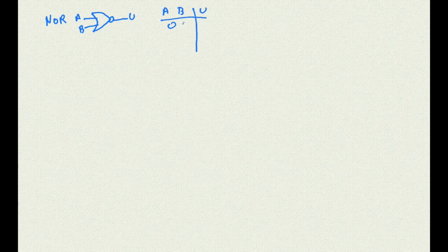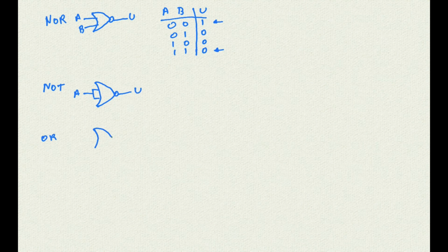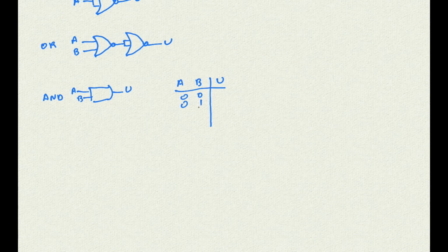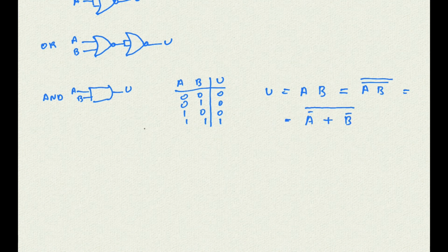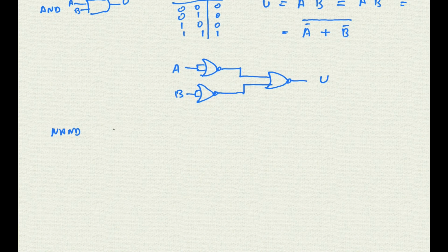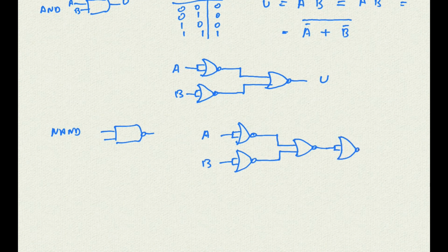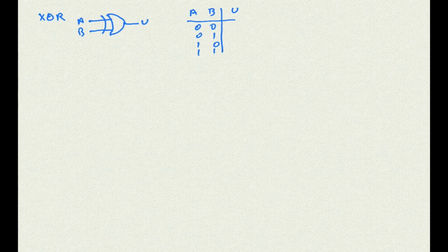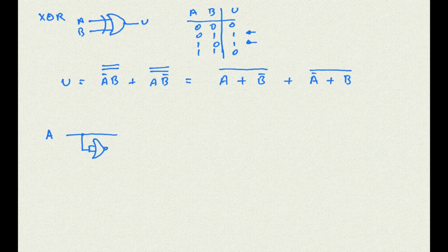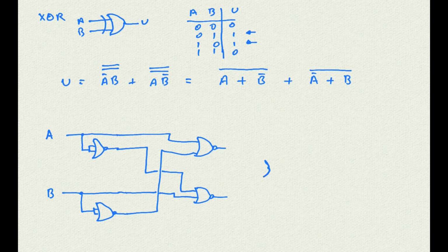One last thing that is left to do is to show you how to make any of the gates we studied using only NOR gates. The procedure is similar to the one we used for the equivalence with the NAND gate circuits, but this time we will need to manipulate the Boolean expressions so that they will be all represented with OR and NOR gates, and so when necessary we will use the other expression for the DeMorgan Theorem, the one that converts NANDs into OR and NOTs. Because of this peculiarity of the NAND and NOR gates that they can reproduce any other gate type, NAND and NOR gates are called universal gates.